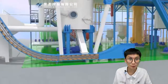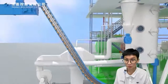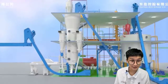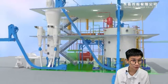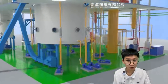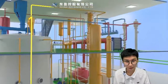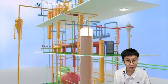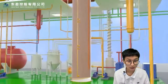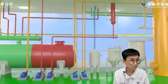And this is what we do for the wet mill. And also, as for the micella, we have another system to evaporate the hexane out of the micella. Because the oil that we finally get is normally for people to eat, so we have to make sure there's no chemical solvent mixing together. So this is our evaporation system for the micella.